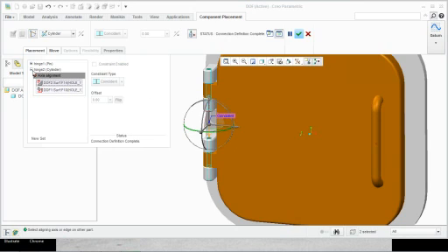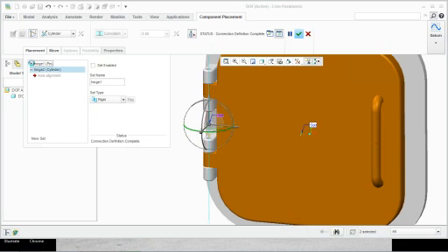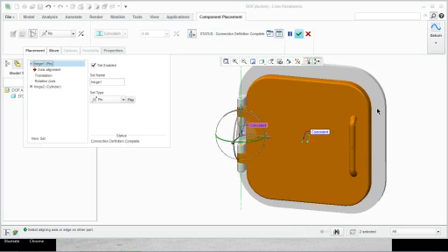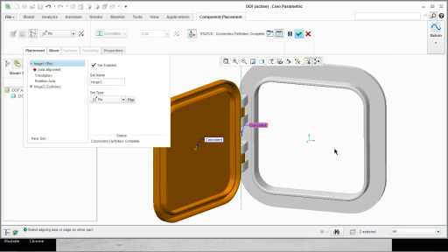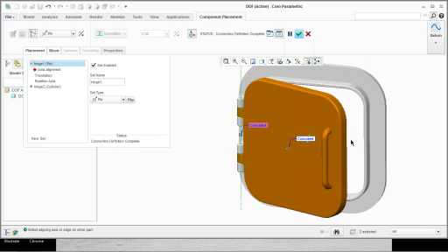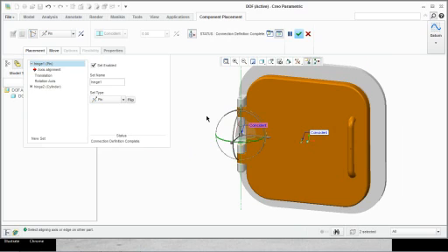Why am I doing this? What is the point over here? The point is, by using a pin connection, this component is connected to this particular component. Okay? And that will allow this degree of motion like that. You don't need to again add another constraint which will restrict or enable the same degree of freedom.